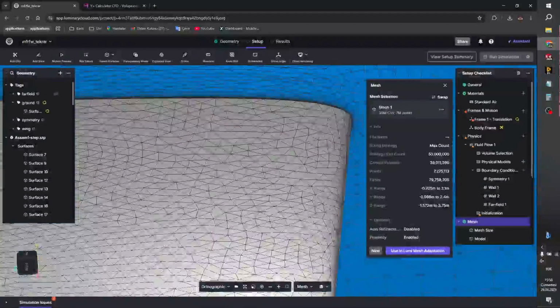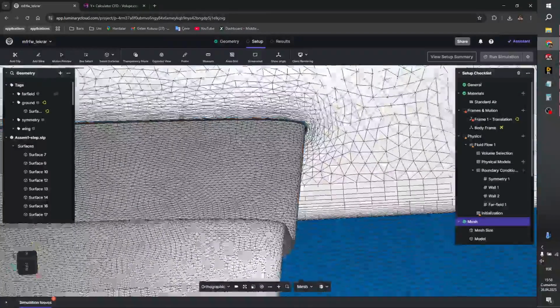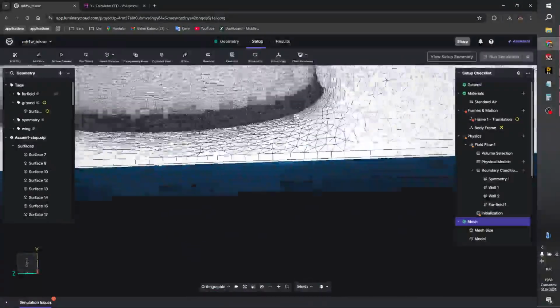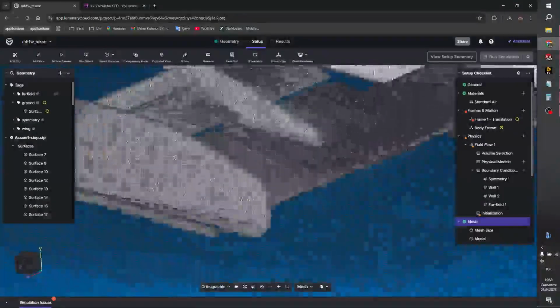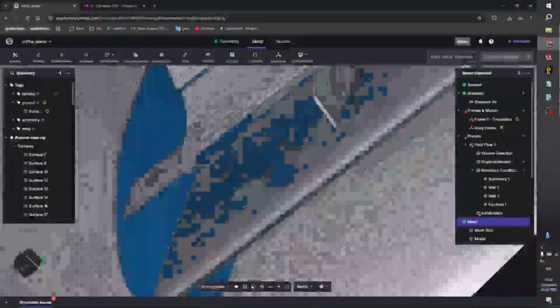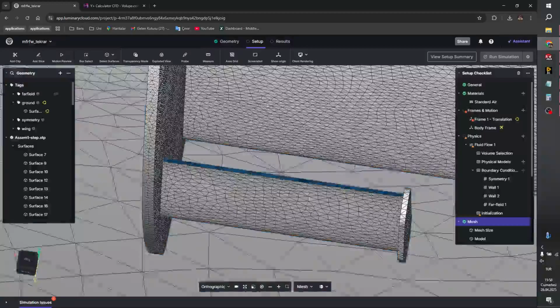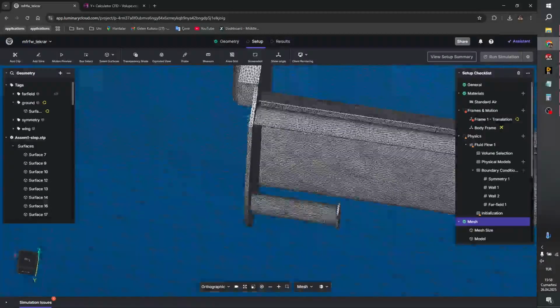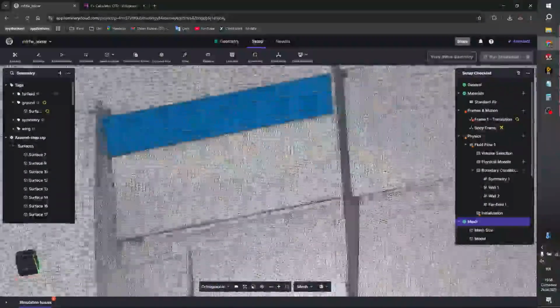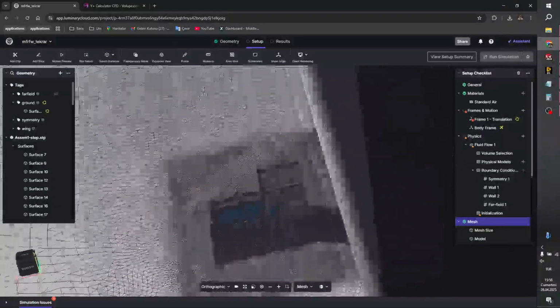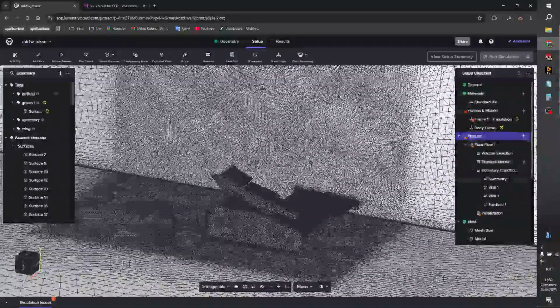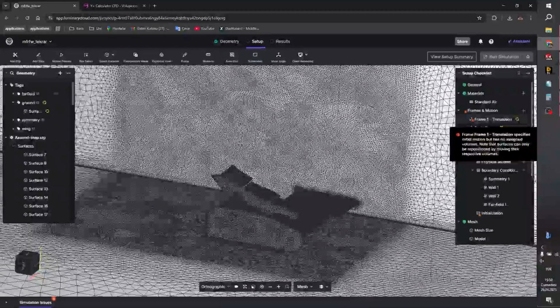Now let us inspect the mesh quality. As expected, the boundary layers have been implemented pretty well, and overall orthogonal quality looks good. Of course, in narrow regions like thin trailing edges, the mesh isn't perfect, but that's due to the simplified approach I've taken for this demo. Thanks to Luminary's tools, these issues can be easily addressed if desired without hassle.